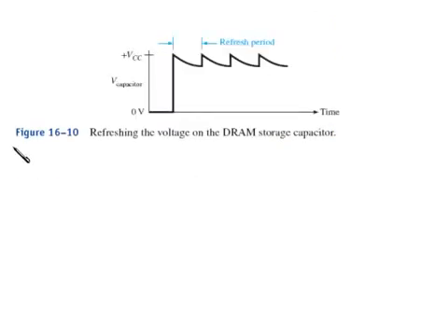Of course, the problem with using a capacitor is that the charge doesn't last forever, so we will have to refresh every 20 or 30 milliseconds. We'll have to read the capacitor. If there's a 1, we have to recharge it, and recharge it over and over again, because it tends to decrease over time. So again, we have to keep refreshing these capacitors.